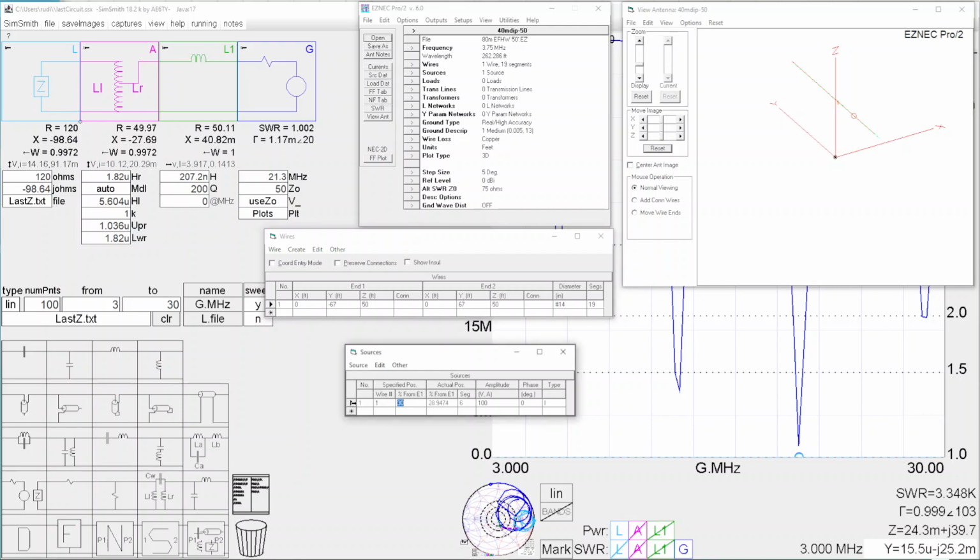Okay, so now I typically feed it 5% from the theoretical end because what happens here is my counterpoise. I need a little bit of counterpoise on the end. So 5% from end E1 of minus 67 feet to plus 67 feet. And it's actually 2.6 based on the number of segments I've got.